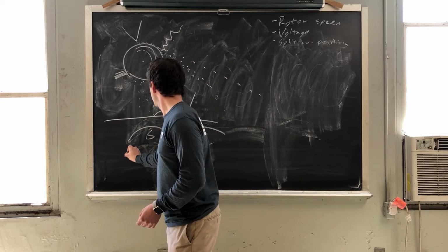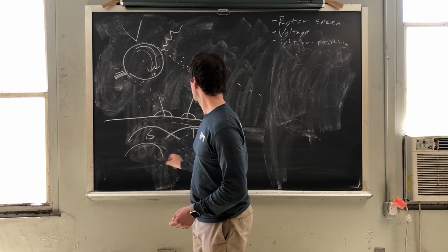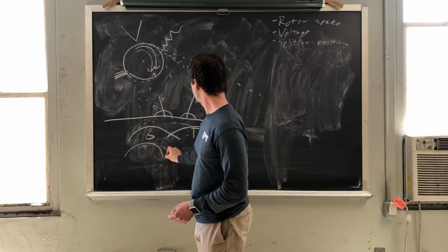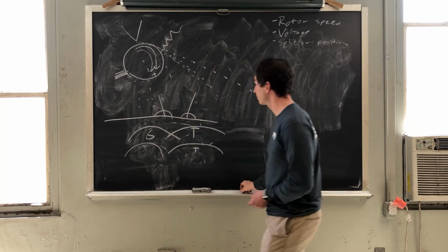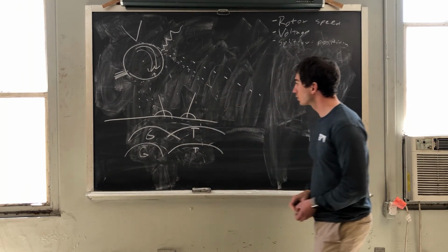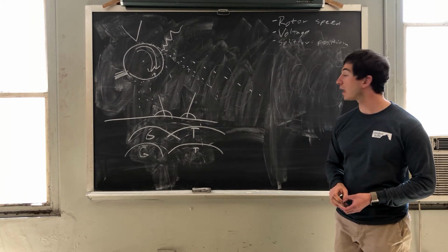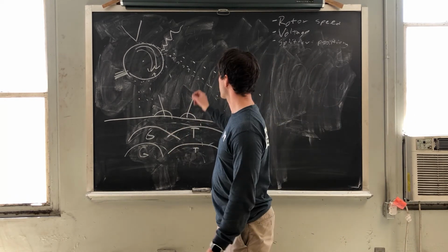But what you might see is more gangue attaches to this rotor for a longer period of time, less flies out, and the titanium you'd hope would look the same. So we probably want to keep our voltage as high as possible without going over this threshold.